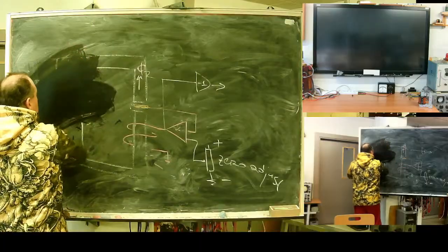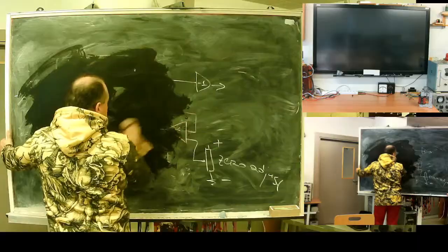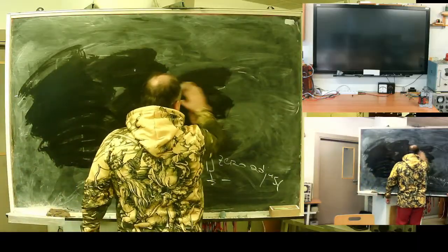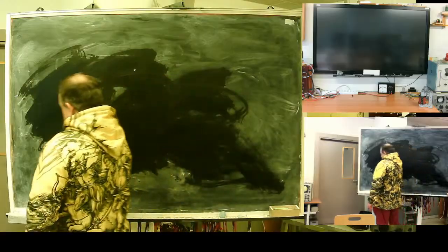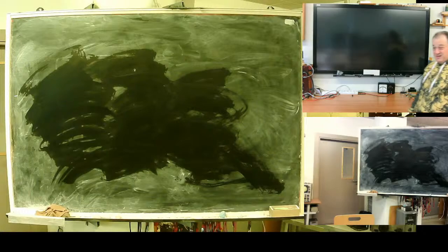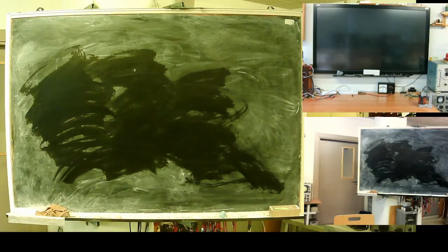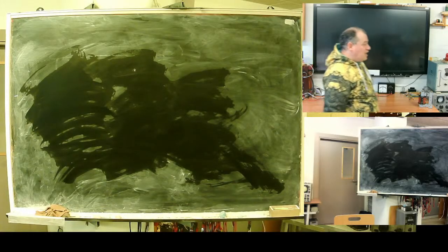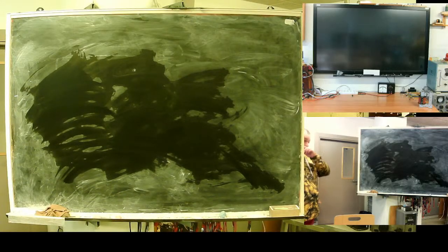The problem is when you need to measure very high DC currents. It's the excitation circuit of a large generator. You may face this problem. High voltage, 600-800 volts, 1000 volts or higher, and very high current, 2000 amps, 3000 amps.